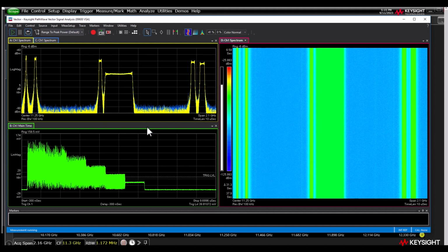I'm working now with IQ data, and that allows me to bring that over into the VSA software and have very fast kind of response. And we also have this waterfall display. The next thing I'm going to do then is turn on the advanced radar, where I can tune each of the 4 channels of the scope to this, and this. These 10, 20, 30, and 40 megahertz wide linear FM chirps, and be able to separate those and do pulse parameter measurements on them.